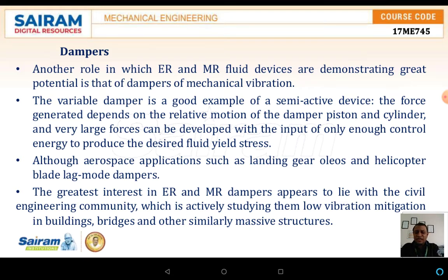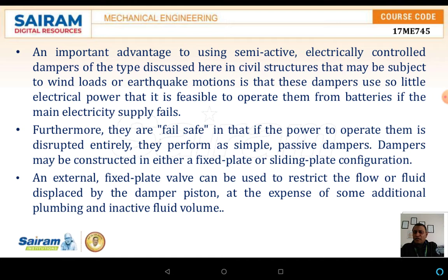other similarly massive structures. The important advantage of semi-active, electrically controlled dampers of the type discussed here in civil structures that may be subjected to wind loads as well as seismic loads or earthquake motions is that these dampers use so little electric power that it is feasible to operate them by means of batteries, and they are very easily controlled and work in what we can say is a fail-safe mode.